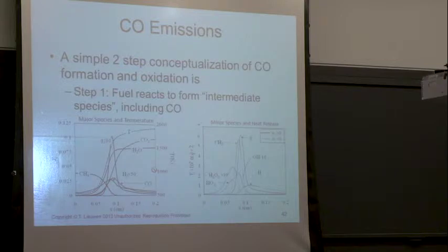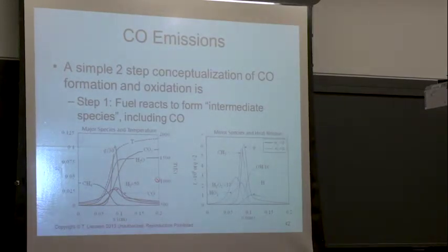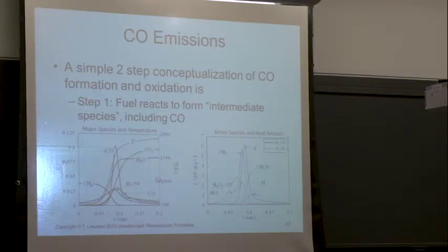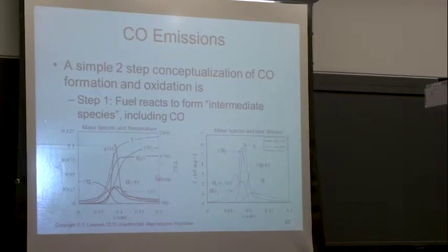Well, let's talk about CO for a minute. As I mentioned, NO and CO are fundamentally different in the sense that equilibrium NO is in the thousands of ppm. You start out with 0 NO, and you're basically climbing towards equilibrium, but you usually don't get there because you quench. Combustion's done, you go into the atmosphere, you cool off, and NO formation rates freeze.